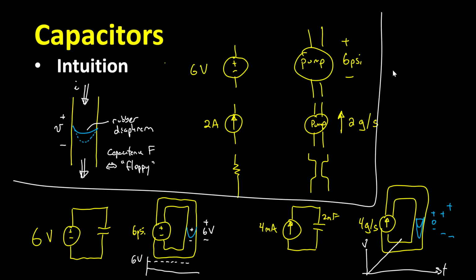As an example of where you might find this useful, say you have an expensive car stereo system, and here's the 12-volt source of your car, and of course any real-world voltage source must have some sort of equivalent Thevenin resistance. This will likely be very, very low. This might be 0.1 ohm, say. In other words, the maximum current that can be delivered by this battery would be 12 divided by 0.1 ohms, or about 120 amps. That's great, except your deep bass thumping speaker might, right at the moment that it thumps, require more current than that.